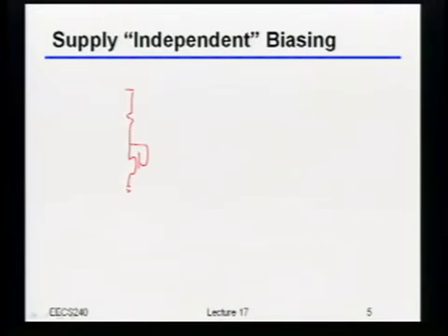Okay? So let's just pretend we do something like this. I have my diode connected device that's acting as a current mirror over here. And then I'm just going to use that, of course, to bias something up. So that's going to be like my I bias at the output over here. And notice what I've done is I've tied this thing just directly through some resistance up to the power supply. Okay? So now the claim here is that if I build this circuit the quote-unquote right way, it'll be at least roughly independent of the supply voltage.